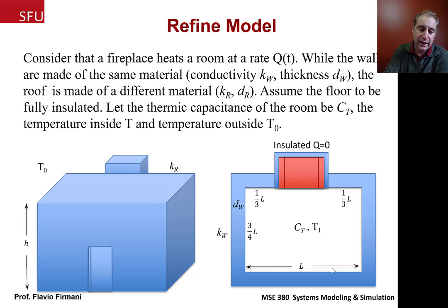And then outside the room, we assumed, as I said, that the temperature on the walls and on the roof was the same as the ambient temperature, but most likely we're going to have a different temperature, and we would have to consider convection, how that heat is being transferred to the ambient, and what is the loss. So there are many things that we can include. We can always